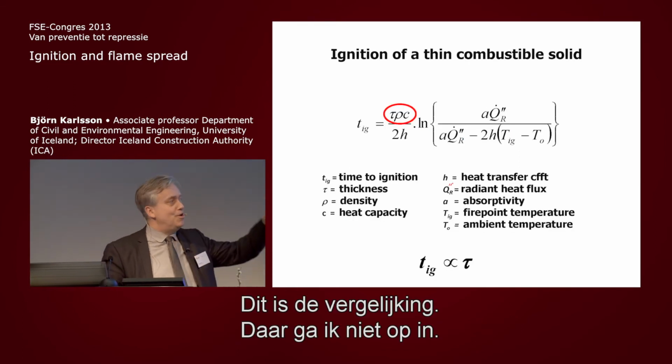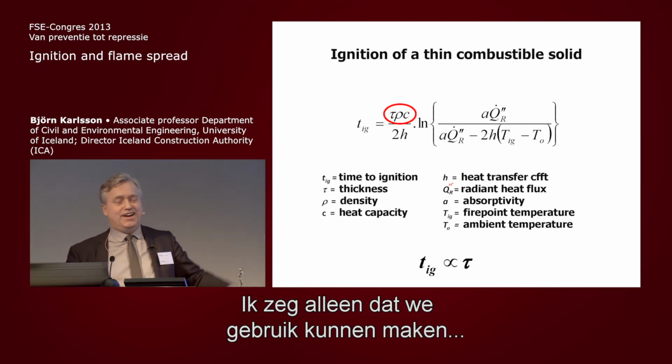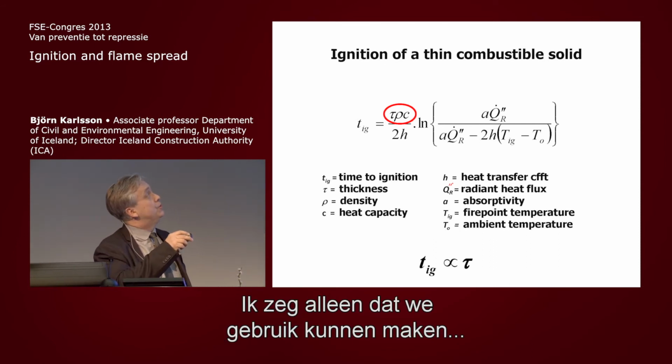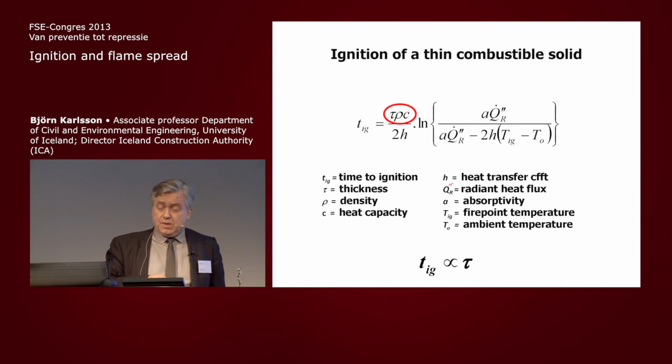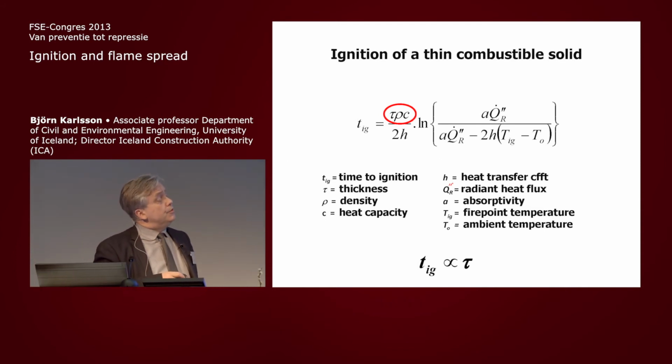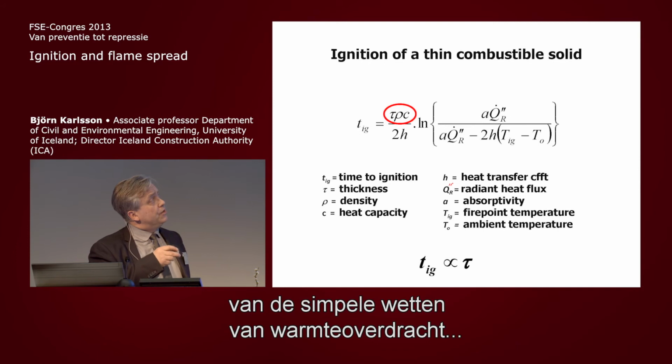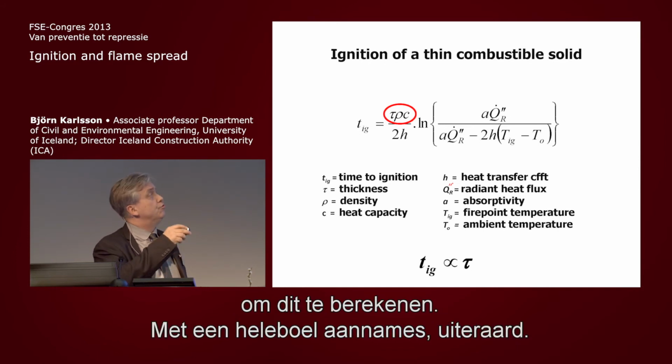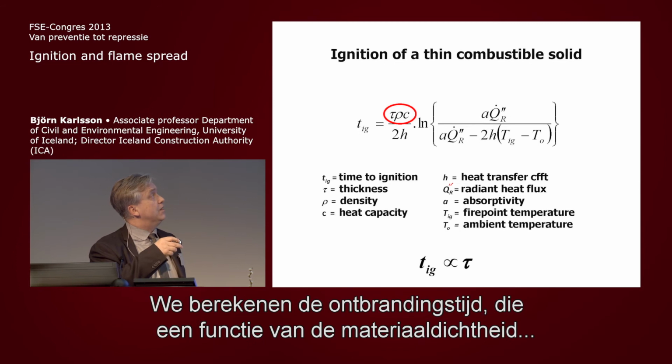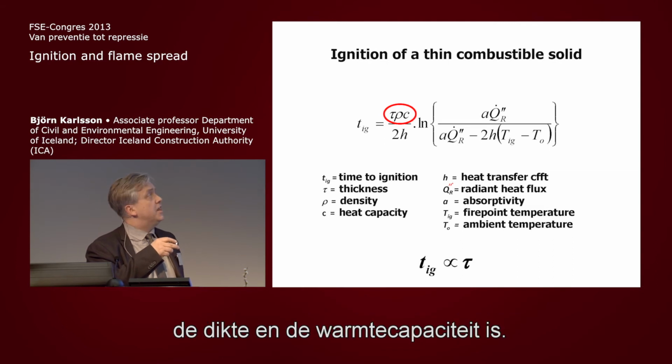So this is the equation. I'm not going to go into the equation. I'm just going to say we can use the laws of heat transfer, just simple laws of heat transfer, to calculate this with a lot of assumptions, of course. So we calculate time to ignition, and the time to ignition is a function of the density of the material and the thickness of the material and the heat capacity.